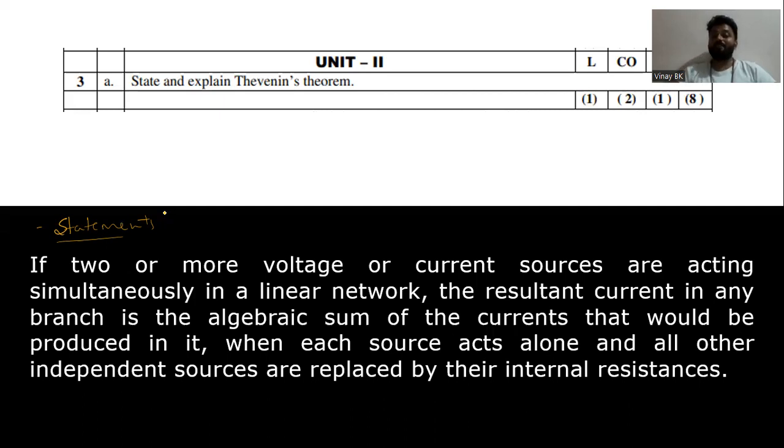If the independent sources do not have internal resistances, the voltage source will act as a short circuit and the current source will act as an open circuit.